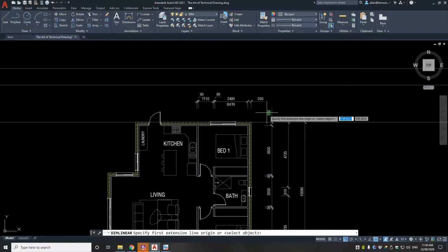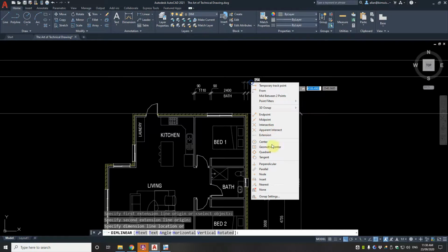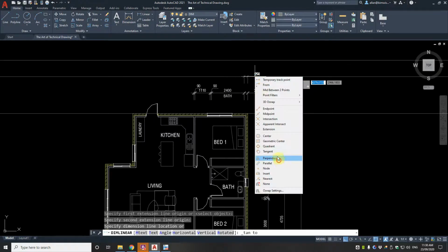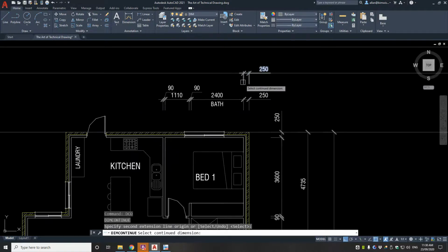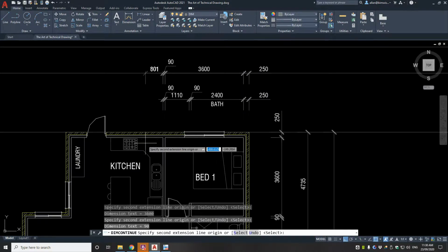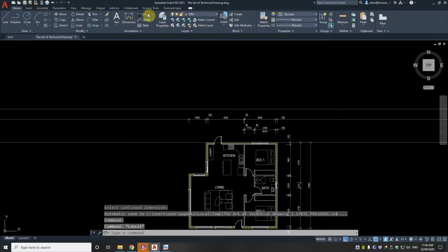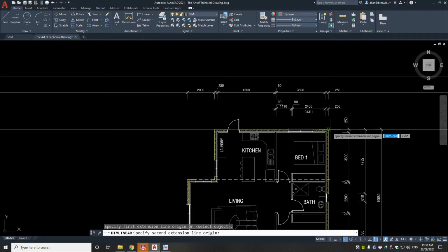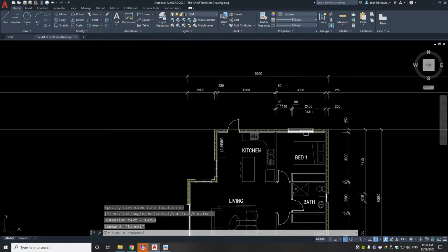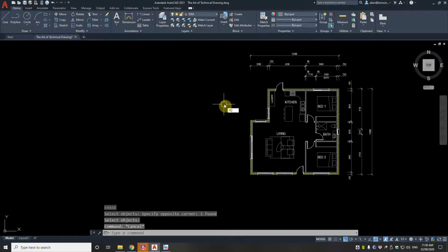And we're going to do some dimensions now of the other bedrooms, which are these ones. So the wall again repeats. I know that repeats below, but often it's easier to read if it's complete and whole, and it does the entire string completed. So that's that dimension done. And I can't be bothered dimensioning that window on that side, because it is in the middle of that bedroom, so you probably could work it out anyway. Overall dimension there, so that side's done.